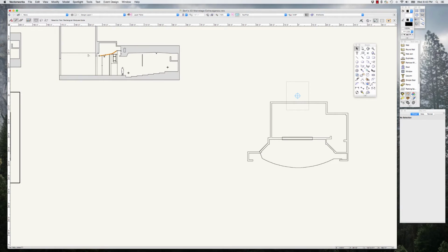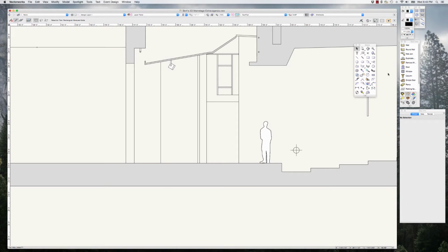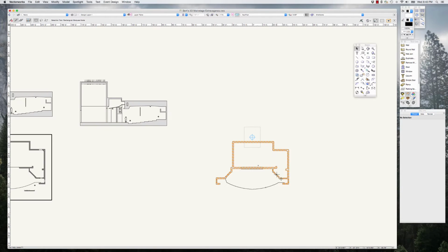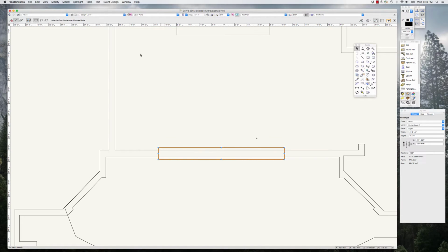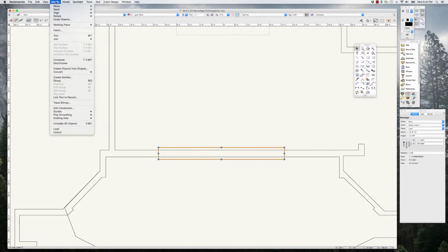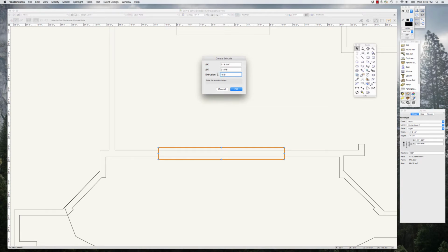So now I need to determine how tall the proscenium is. I'm reasonably sure it's 13'11", but let's see what our drawing says. Our drawing says that it's 13'10 and a half", so I'm going to call it 13'11". That's close enough, because who knows if this drawing is accurate? And I'm reasonably sure that we've measured the proscenium at 13'11". So what I'm going to do now is extrude this 13 feet 11 inches. Model, extrude, 13 feet 11.